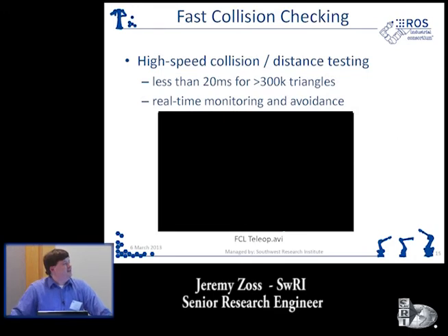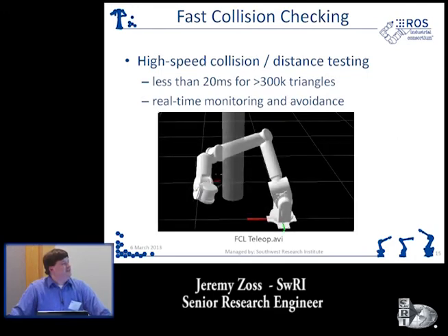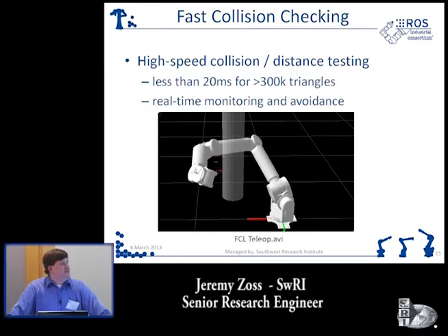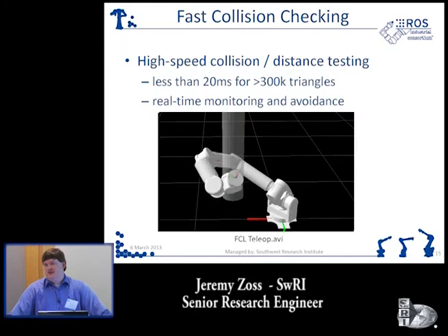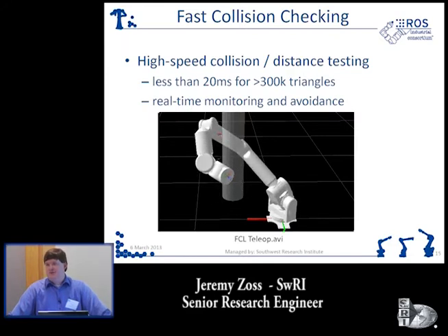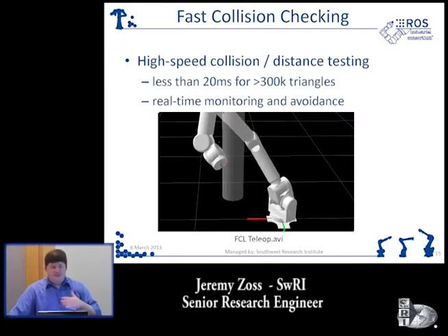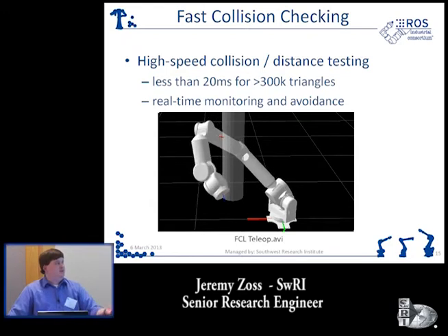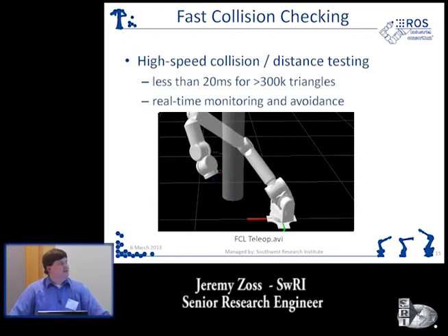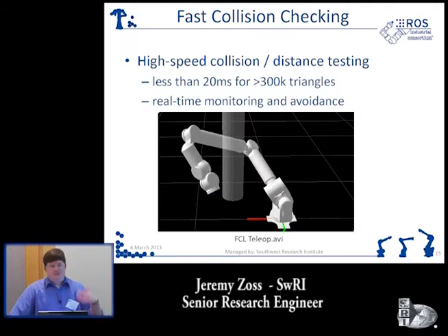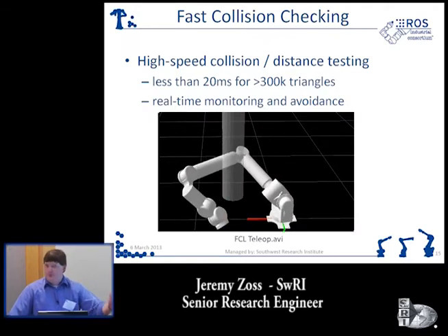We talked already about collision planning, but the real point to emphasize here from an industrial perspective is how those collision and distance checks really are real time. This is the kind of thing that as your robot is running a pre-programmed path, it's not just something it can do ahead of time, but while the robot is actually executing, the code's fast enough to be calculating those distances and to be able to send a signal to the robot to say stop or avoid that obstacle